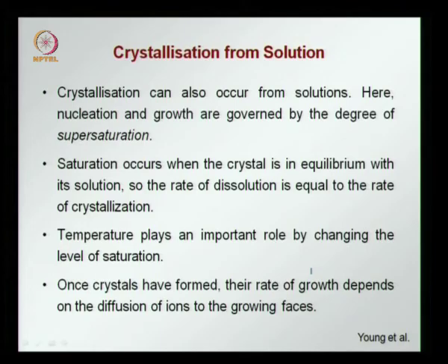When we talk about crystallization from solution, temperature also plays an important role. Crystallization from solution is governed by the degree of supersaturation. Only when the solution is supersaturated do you have nuclei occurring and the nuclei growing. At saturation the crystal is in equilibrium with the solution, that is, the nuclei are dissolving at the same rate at which they are forming, so the rate of dissolution is equal to the rate of crystallization.